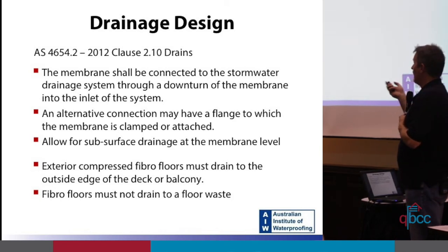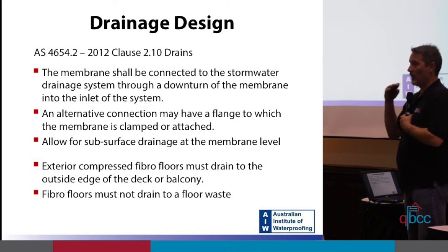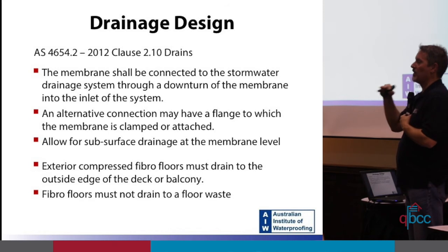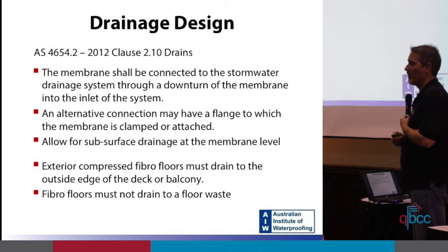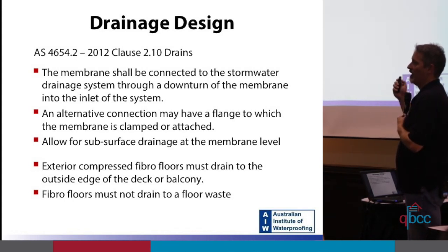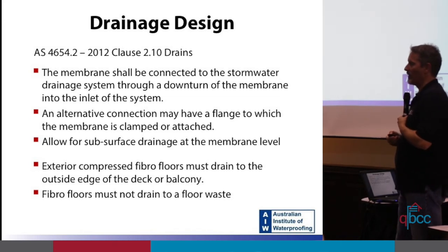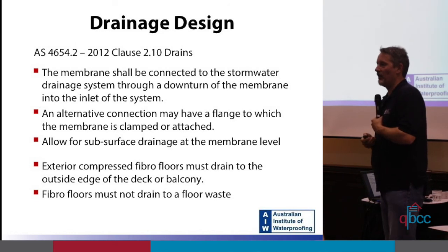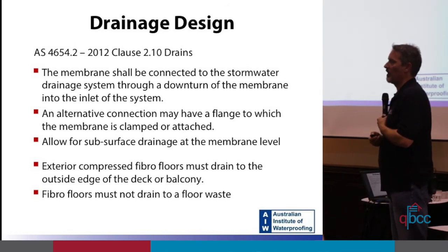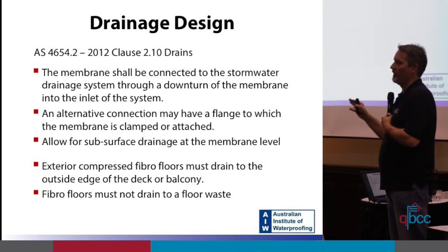All right. The alternative connection is through puddle flange. The internal waterproofing standard says you must use a drainage flange or puddle flange for your drainage connection. The external waterproofing standard gives you both options. All right. Believe it or not, the standards are actually written by two different committees, so that's why the difference. AIW's advice, use a puddle flange or a drainage flange everywhere and make sure they're recessed.